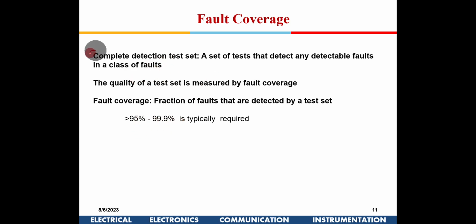Like I explained earlier, once we have the full fault list, we generally run a random algorithm to find which are easy and which are difficult. The easy ones run much more quickly when we run random test generation, because you are giving random tests and covering many faults. For the difficult ones, you have to take each fault and do all this sensitization, justification and propagation. So it is a time consuming process. If the random test generation covers 95 to 99%, you may want to skip some of the faults to save time. So time is an essential element.